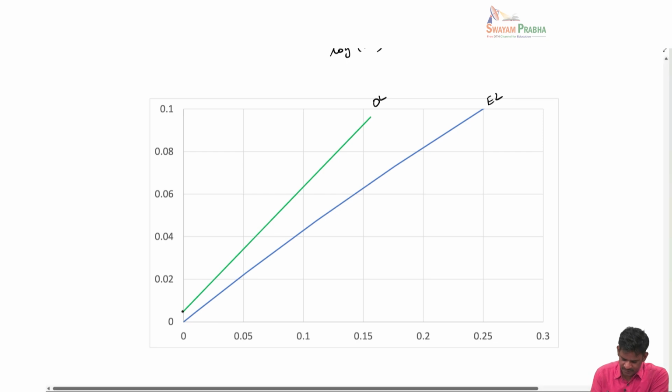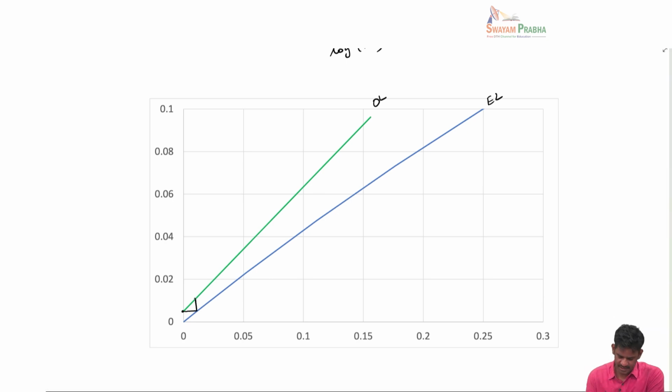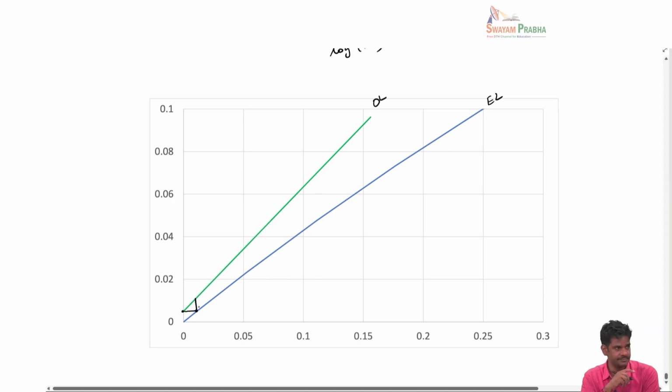So we start from here and go horizontally and touch the equilibrium line, and I go vertically. So this staircase completes one equilibrium stage such that the outgoing streams here are in equilibrium, and from this point I go horizontally and then I go vertically. Okay, this is the stage 1, this is stage 2, stage 3, stage 4, stage 5.